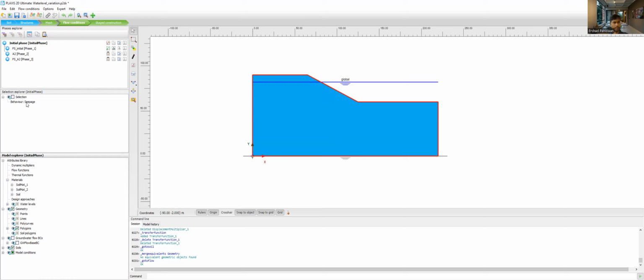In the groundwater flow, this is called the Neumann boundary condition. So in this area, we can input this value if we like. I click here, like I want to use this as a boundary condition, then I can select seepage, infiltration, or something like that.